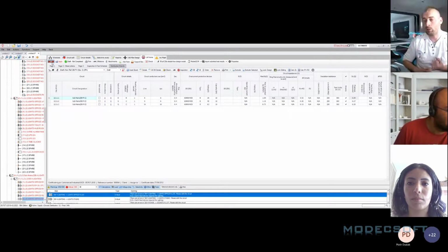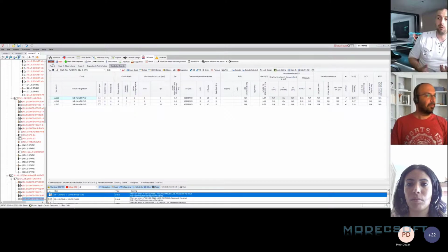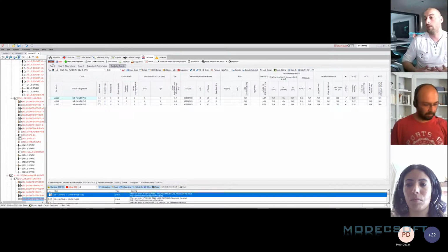It will pick out issues where you've got selectivity issues between your devices, and it'll do a reverse design check against whatever is currently installed on that system. So everything is a bit more thorough in terms of the data, and we try and make the data really meaningful for anybody who is managing life cycles of particular buildings for their clients.